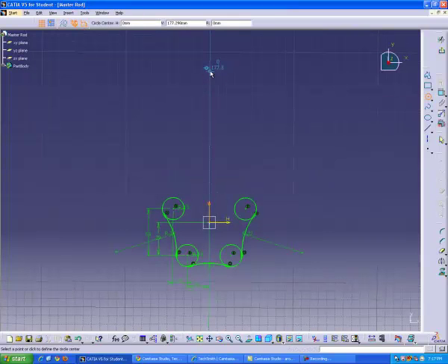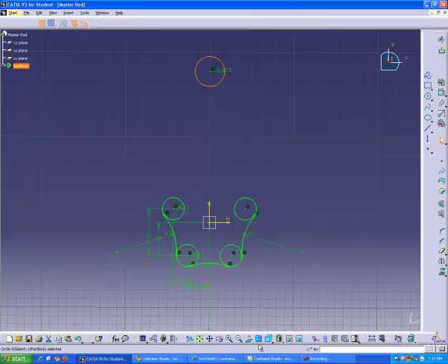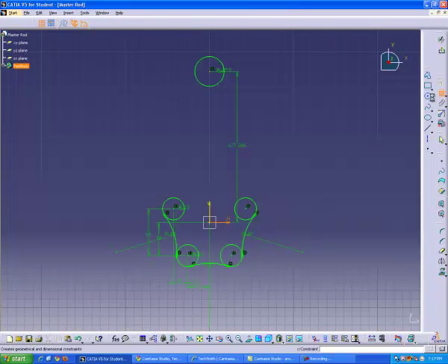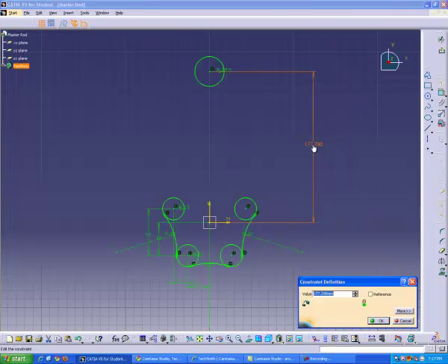We're going to create a single circle that's along the vertical axis that has a radius of 35 millimeters. And that should be 250 millimeters away from the axis.